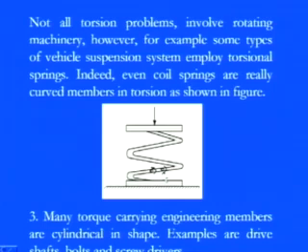So, whenever we want to design those things, we have to consider how these moments are taking place and what the effective area is under which these moments act. Once you set up the twisting moment, then the immediate question, as I told you, is what the shearing action will be under this twisting moment. Once you know the twisting moment as well as the shear stress, the next is how many coils there are, the n number of coils, and what the effective diameter of these coils is.